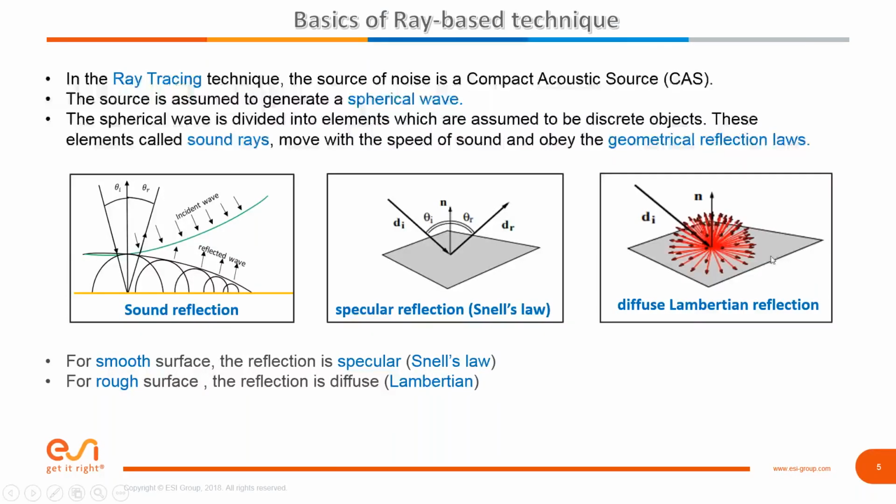So we have those two options, and the other thing we have when we talk about geometrical reflection, we have a really good way of modeling treatments, trims, noise control, multiple layers of fiber, foam, mass barrier, air gaps. So those also take into account the incidence angle of the sound wave in terms of how it absorbs and reflects. We do model full details of the trim, multiple layers, complex impedances. So that's much more advanced than a regular ray tracing code, which might only model absorption as a function of frequency. We're modeling complex impedances or multiple layers, if you like, and taking into account the effective angle. That keeps with modeling the full details of sound package treatments and trims.